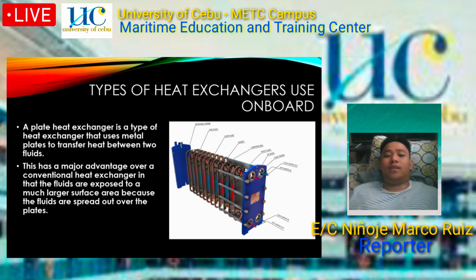A plate heat exchanger is the lowest cost option because it can achieve high heat transfer coefficients, with pure counterflow giving the most efficient heat transfer and lowest surface area. Maintenance cost is also reasonably low, especially compared to a scraped surface heat exchanger.